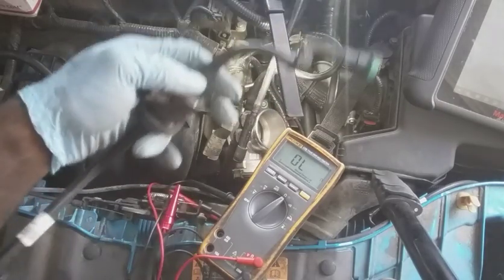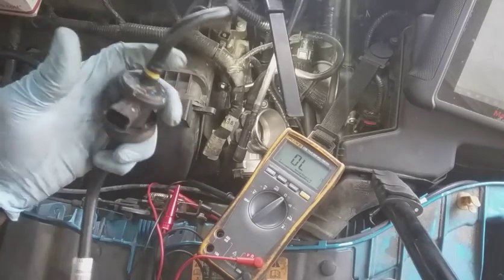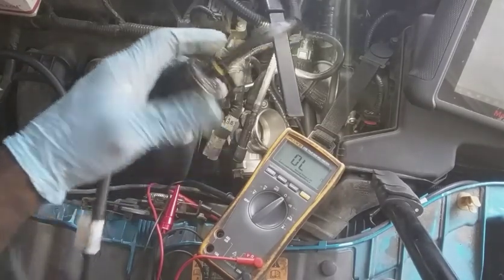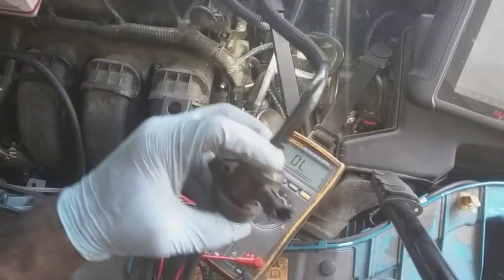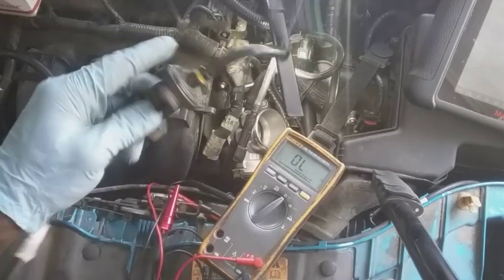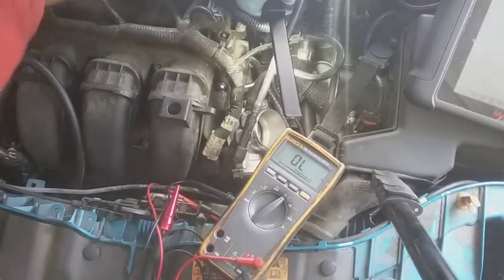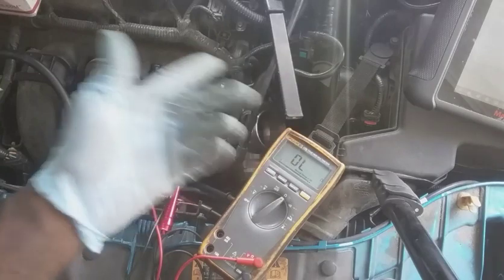Because when you're decelerating, you're in vacuum and coming to a stop, it's going to detect that vacuum leak instead of closing or going through its pulse width modulated state, or lowering the pulse width modulated state, so it'll stay closed longer. So that's why you get the stalling condition. So I'm going to get a new one, put it on there, and we can vacuum test a new one,